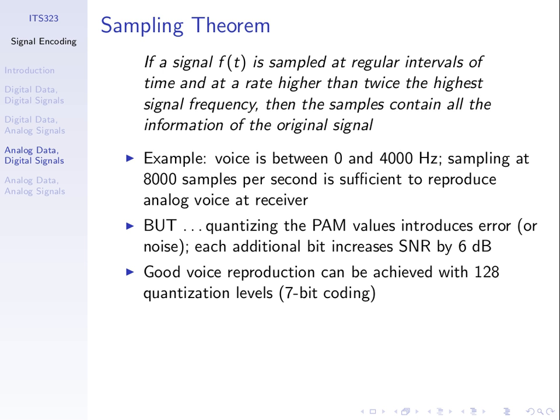So when a codec is chosen, you need to make that trade-off between the sampling rate and the number of levels. Increasing them gives better quality, but more data needs to be stored to represent that analog input. That is, either a higher data rate to transmit it, or more bits are needed to store it, if you're talking about storage on a hard drive or some medium. There are many different codecs. PCM is the main one we've looked at, but there's no compression in there.